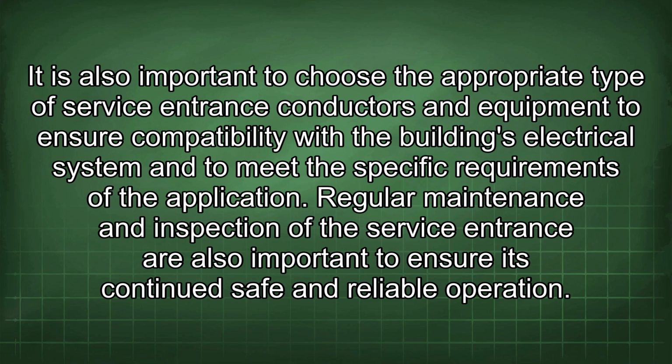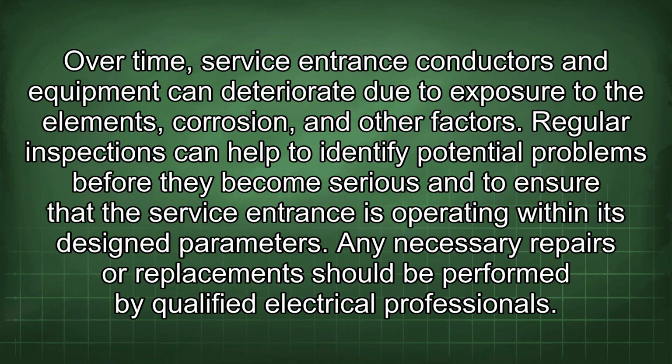Regular maintenance and inspection of the service entrance are also important to ensure its continued safe and reliable operation. Over time, service entrance conductors and equipment can deteriorate due to exposure to the elements, corrosion, and other factors. Regular inspections can help to identify potential problems before they become serious and to ensure that the service entrance is operating within its design parameters. Any necessary repairs or replacements should be performed by qualified electrical professionals.